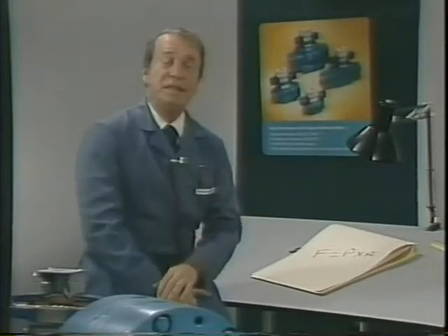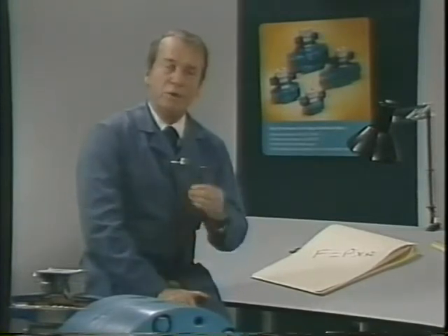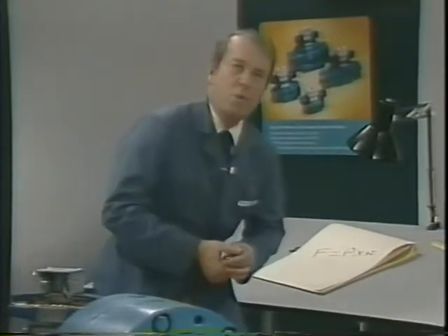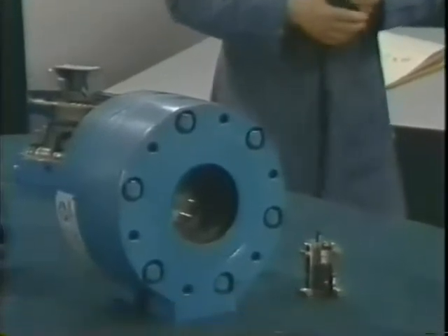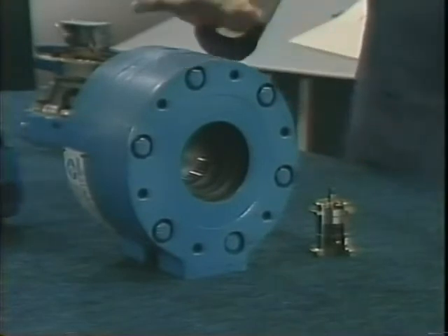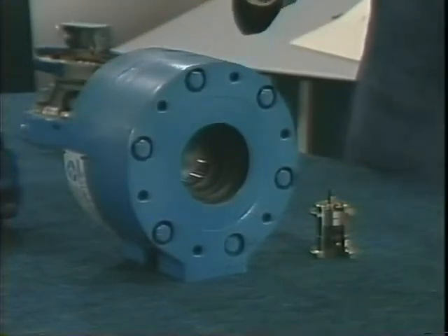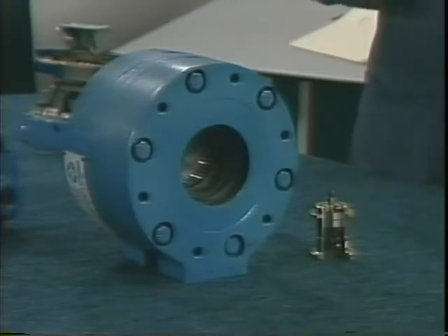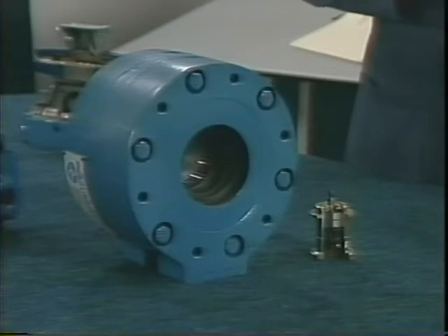Now, the second basic motion we can achieve hydraulically, rotary motion, usually calls for a hydraulic motor. Motors come in a wide variety of sizes and shapes, from tiny ones which may provide only a few pound-inches of torque to huge models which develop literally thousands of pound-feet and can flip over a boxcar with ease. The most common motors, and pumps for that matter, are vane, piston, and gear type. But since the functions of all three motors are the same, we'll just use the ANSI symbol to represent them.